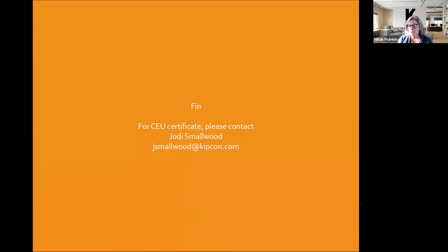Older pavement, seal coating does nothing. That's when it's just aesthetics. If you want a darker looking pavement, you can seal coat it, but you're not getting the benefit of what seal coating is intended to do if you seal coat older pavement. Also, be aware that when you seal coat a pavement and a snow plow goes through in the winter, you get white streaks where the plow blade hits it. You see that on seal coated driveways very often. It's really a matter of personal preference if you want to seal coat your older pavement or not. It's really an aesthetic thing for older pavement.